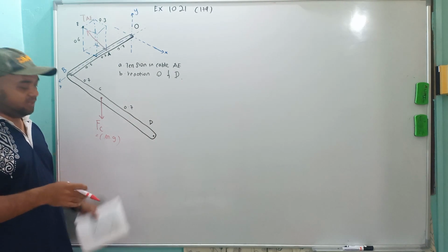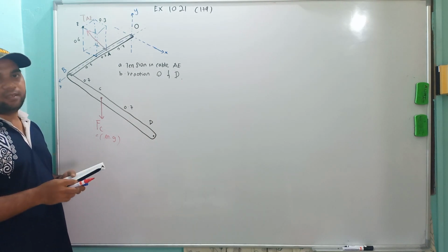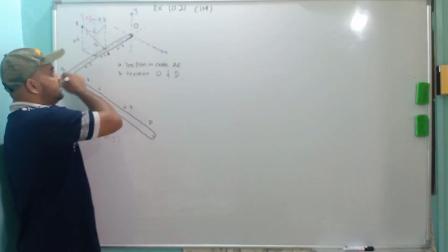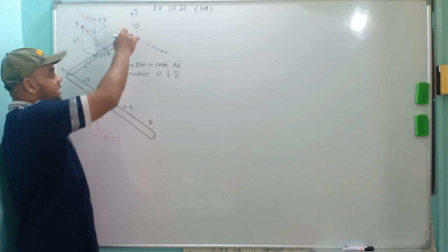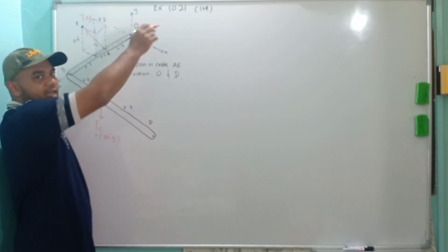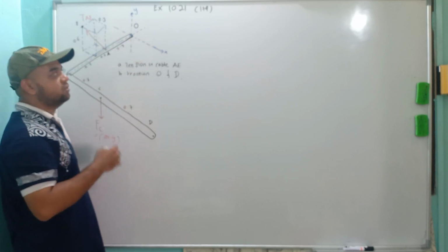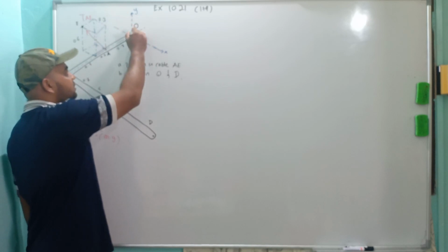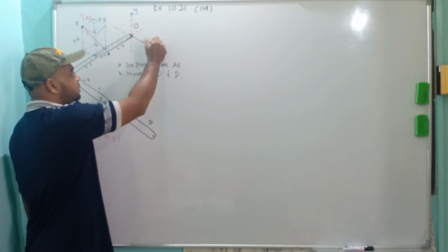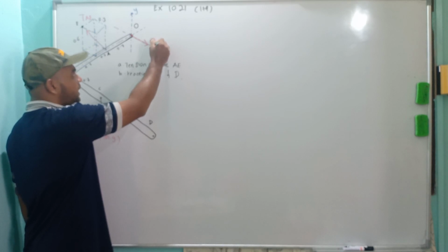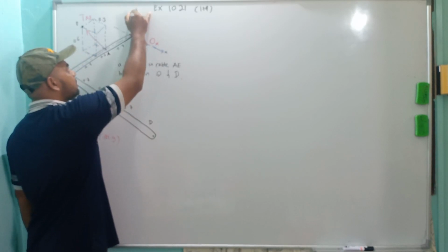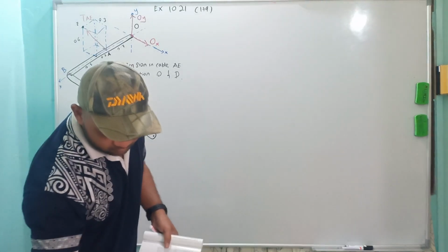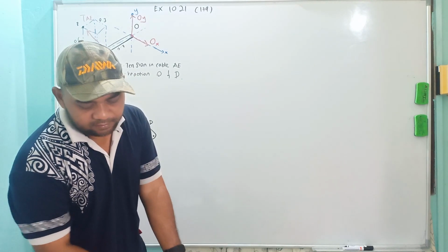Please refer to the table for the reaction forces if you are not comfortable with them. So in the Z direction there is no force, but the bearing holds the component from moving in the X and Y directions. So there will be OX and OY, and nothing in the Z direction.